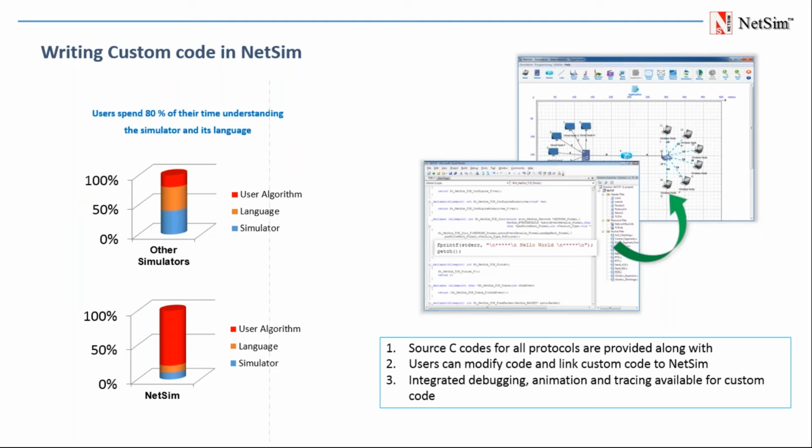So this Netsim understands the DLL extension file. So anything we want to edit or create our own protocol, that has to be saved in a DLL extension. So we have to just save the DLL extension and copy that DLL file into the bin folder. Then we can access those DLL files, and we can access our DLL extension file and the protocol. So that I will show you in custom code implementation how we can do this.